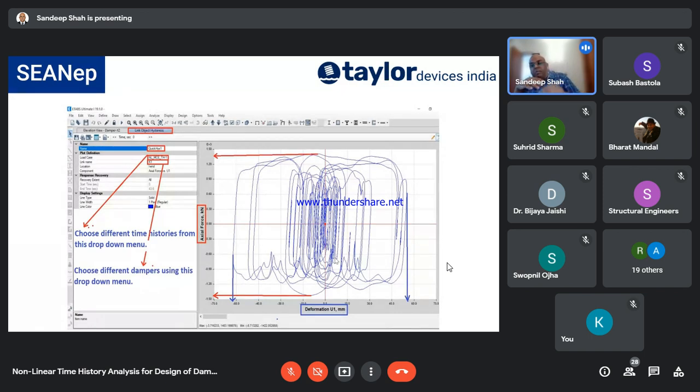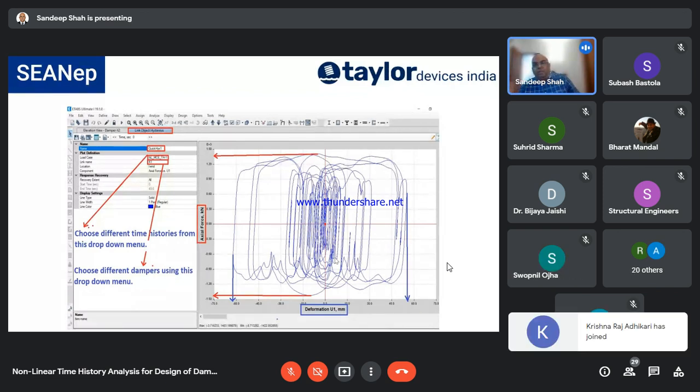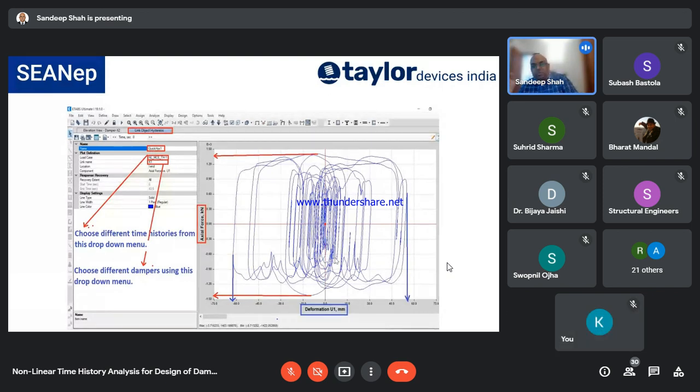Now if you recollect, we went through a lot of provisions where in certain conditions you have to increase these values by 30%, and in certain conditions you have to further take some enhanced limit over and above this, right? So this is the nominal result property. So when I use those safety criteria of ASCE, this about 65 mm may reach 100 mm, and this 1350 kilonewton may reach 1800 or 1900 kilonewton.